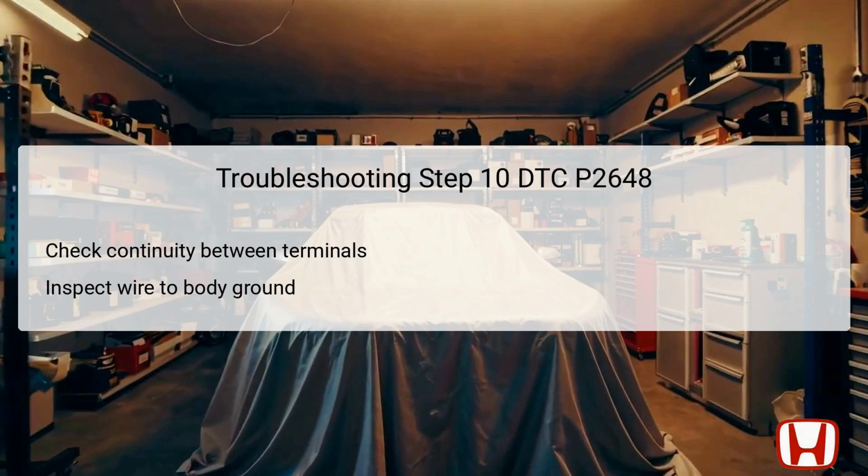If continuity is confirmed, this shows that the wiring is sound and there are no shorts or breaks. However, if continuity fails, it suggests a short circuit in the wiring or a cut in the cable, requiring further investigation and likely repair. Accurate continuity checks are vital to ensure the electrical system operates as designed and to address any issues effectively.